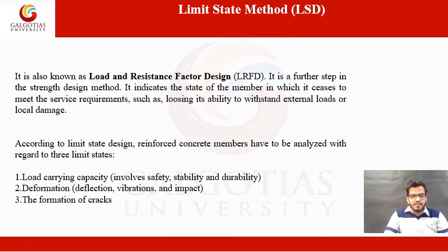According to limit state design, reinforced concrete members have to be analyzed with regards to three limit states. The first one is the load carrying capacity, which involves safety, stability, durability. The second one is the deformation, the deflection, vibration, and the impact. And finally, the formation of cracks. So this method is used by analyzing the typology of the framework so that these three types of parameters can be analyzed throughout the life of the building.